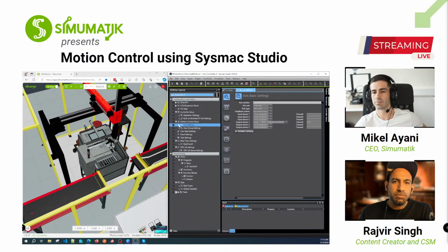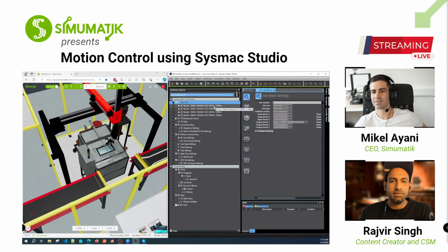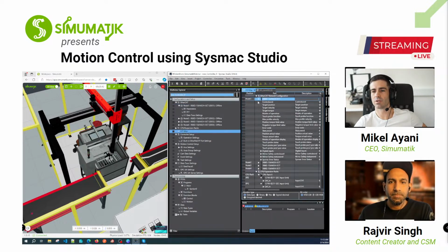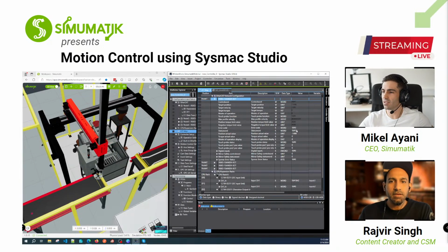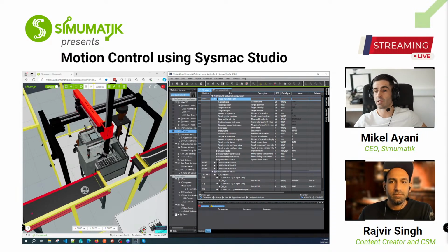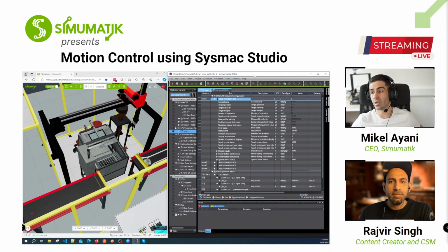And maybe you can also mention that before we come to the axes, we also install some drives. If you go to the Ethernet on top, you will see that 4 hardware drives are added, and these are linked to individual axes. And you were mentioning before that we can see this communication being kind of simulated, even if we are in simulator mode. We are running against the simulation. So basically, I just click play here in the simulation, and we are running everything without any hardware.